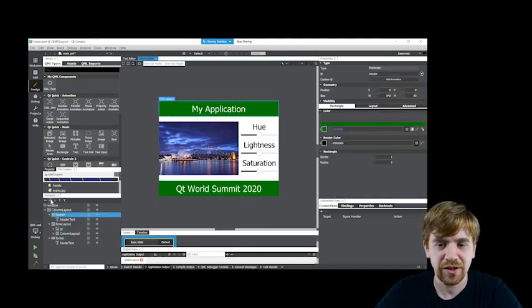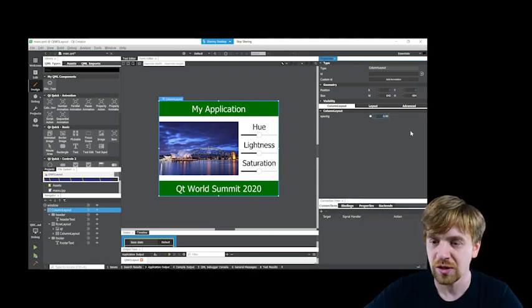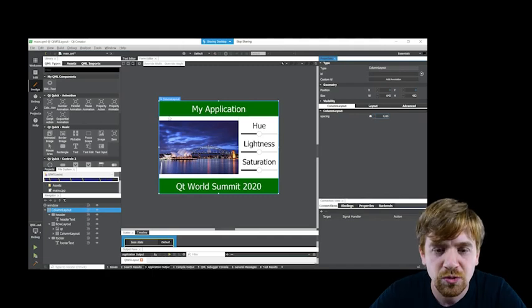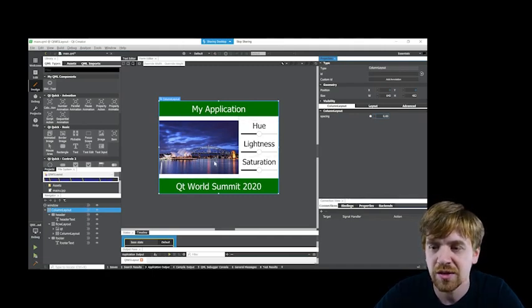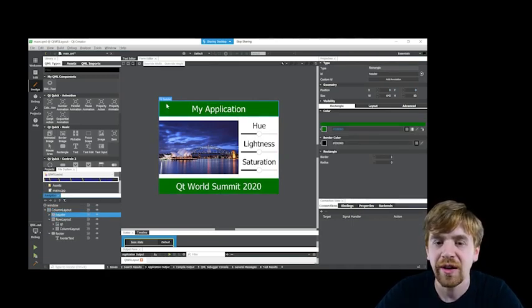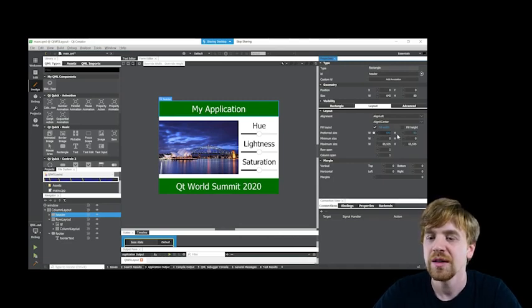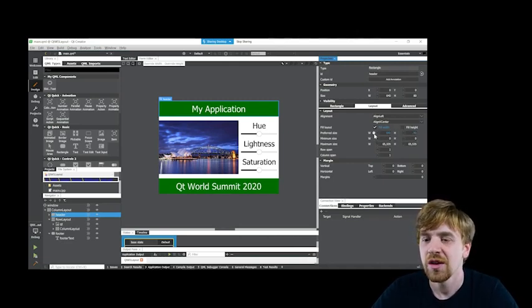Now we can define, for example, for each one, first the spacing that we want. So here I don't need any space on my column layout. I don't want any space between my footer, my header and the center of my screen. So there is no need here. For my header, what I need to define is just that my green rectangle is filling the width. So it's what we can define here, filling the width. And here we can see that it has been set by default, because it's in blue, the preferred width size and the height size. So for the width, actually we don't need any width because it will always fill my screen, so I will reset it.